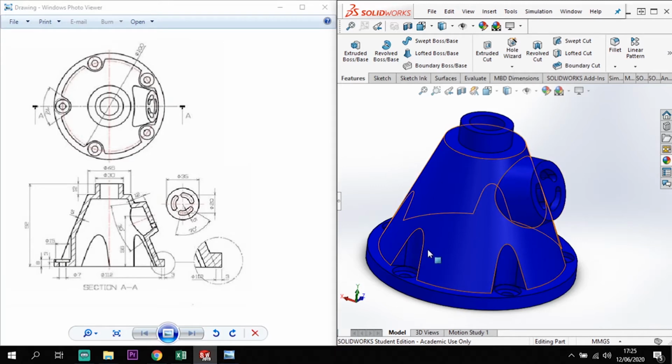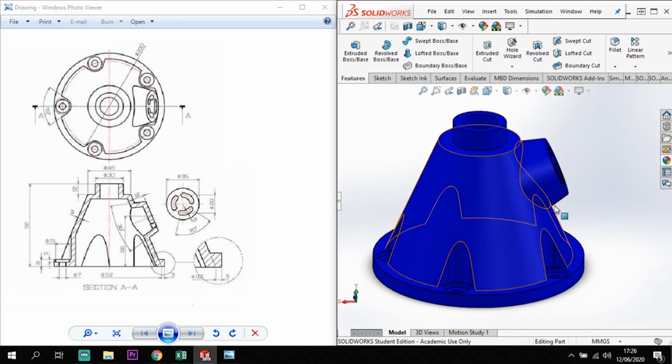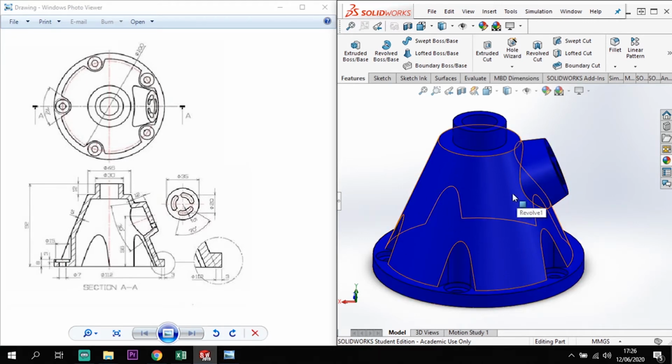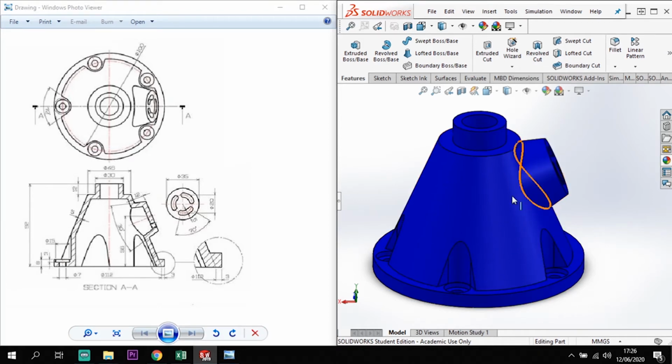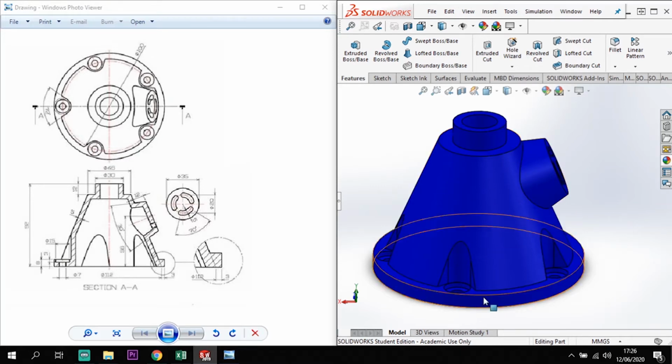Once I've got those 5 sections cut out, I'm going to add in this add-on at the side here, which is set at 90 degrees to that edge coming out. Once I've got them in place, I will then shell it. The shelling feature means the inside works out exactly how we need it. After I've shelled it, I can add on this step at the bottom, the ring at the bottom and the 5 holes in that, so I'll add that on last.